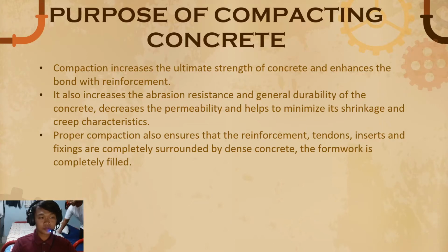Next, purpose of compacting concrete. Point 1, compaction increases the ultimate strength of concrete and enhances the bond with reinforcement. Point 2, it also increases the abrasion resistance and general durability of the concrete, decreases the permeability and helps to minimize its shrinkage and creep characteristics.